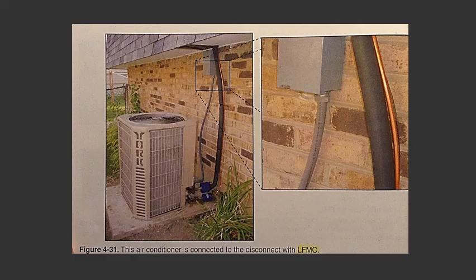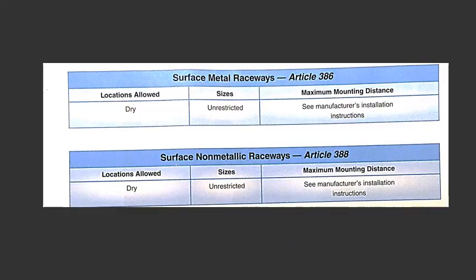Surface mount raceways. Surface mount raceway is an assembly of two sections, a base and a cover, that is generally rectangular or flattened oval. Sections are 10 foot long and range from 3/8 to 3 inches high in form and from 1/2 inch to 4 inches wide. Surface mount raceway is constructed of steel, aluminum, or plastic.